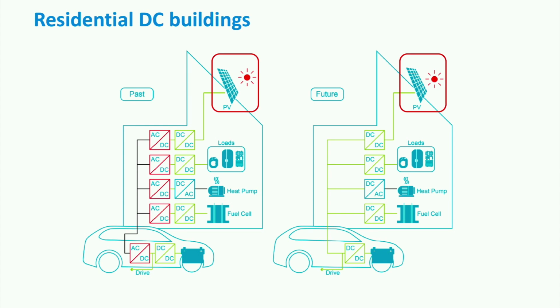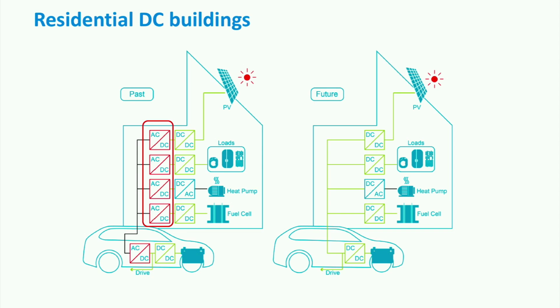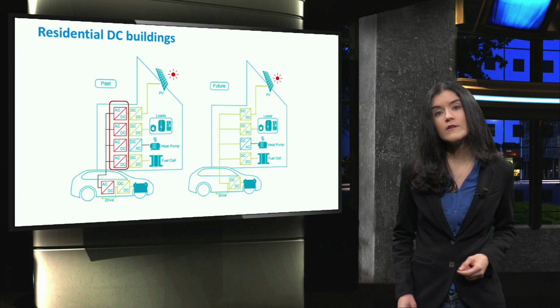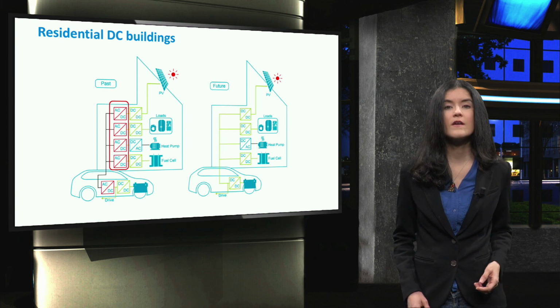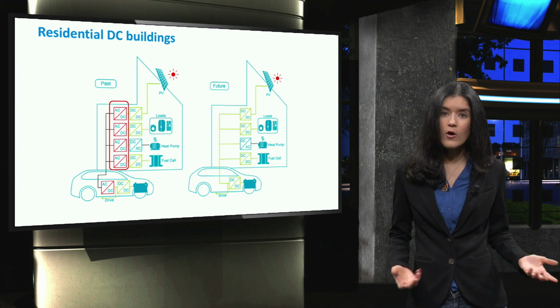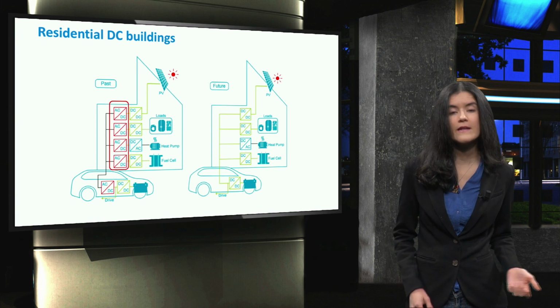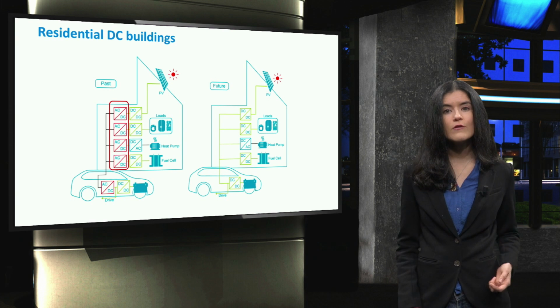This has the potential to eliminate the large number of AC-DC and DC-AC conversion losses that occur in traditional AC households. Moreover, several appliance manufacturers are supporting the modification of products and supplying products that are DC ready, making them easily available for households with DC grids. The control in these grids mainly aims to minimize the energy exchange with the main grid through the use of storage elements, while optimizing the operation of the renewable energy sources and sometimes selling energy to the grid when it's profitable.